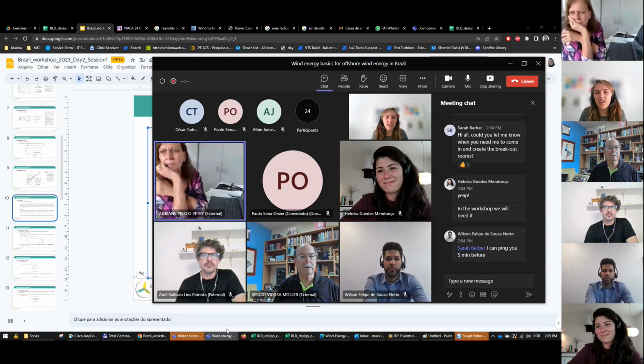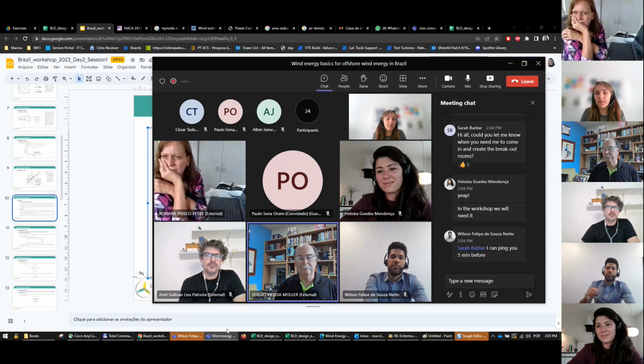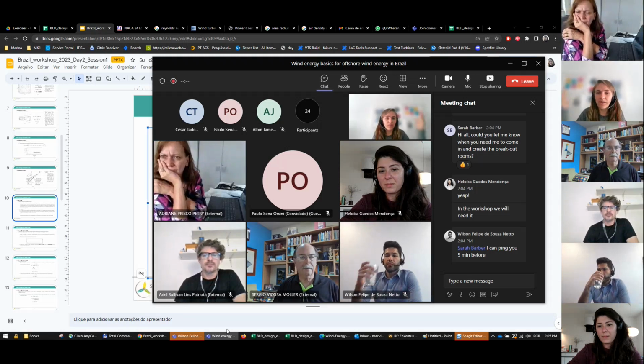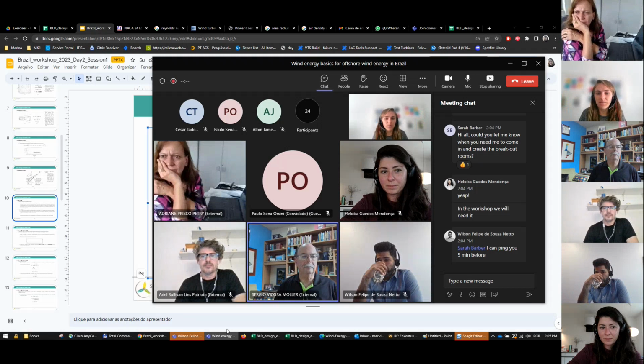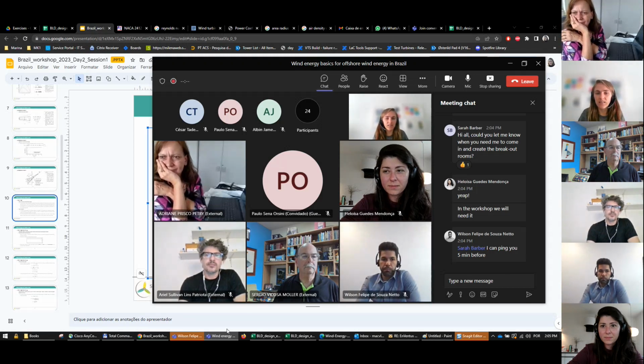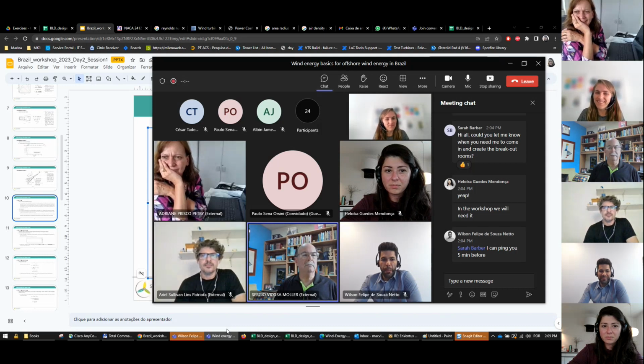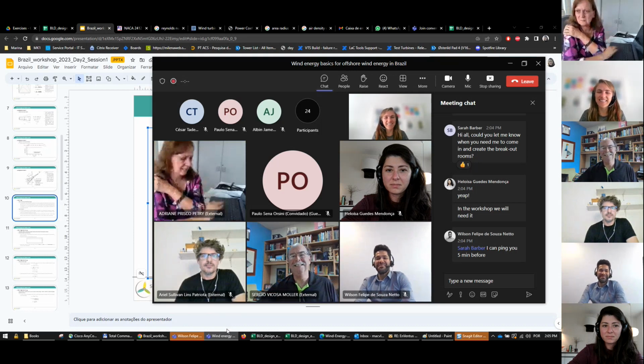You can have a rated power and a rated wind speed of 25, but if you only reach 25 three days of the year, in the end it is not a good solution. Okay, the answer is measure and decide.